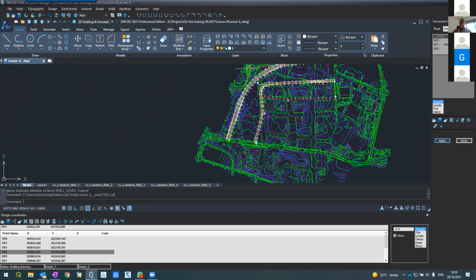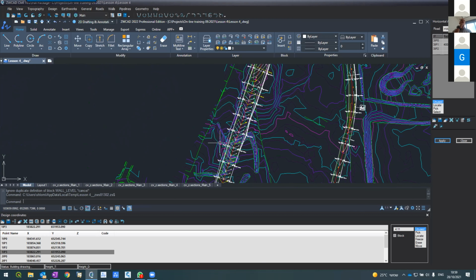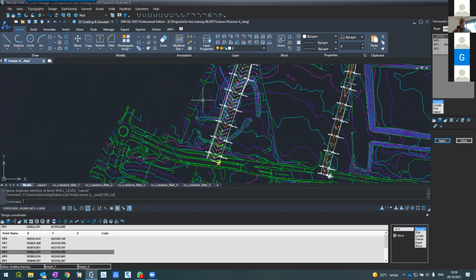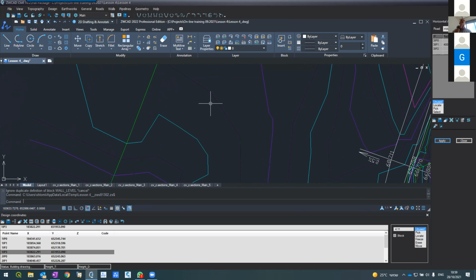Now I'll use the same technique, but I'll add another coordinate here. Listen up, pros, especially for you. The IP is here. This is the exact point that I want to use. This one. I'm using pick to create another point. The system will call it point 1005. Why? This is what the software wants. I can change it later. 1005, I'm happy. And I will put it somewhere here. Or you know what, exactly here with object snap. So I have a new point, for now not an IP. It's just that I've added a point here.